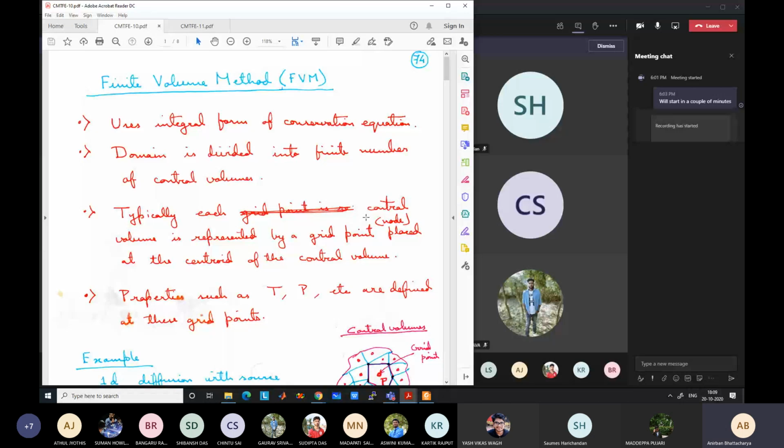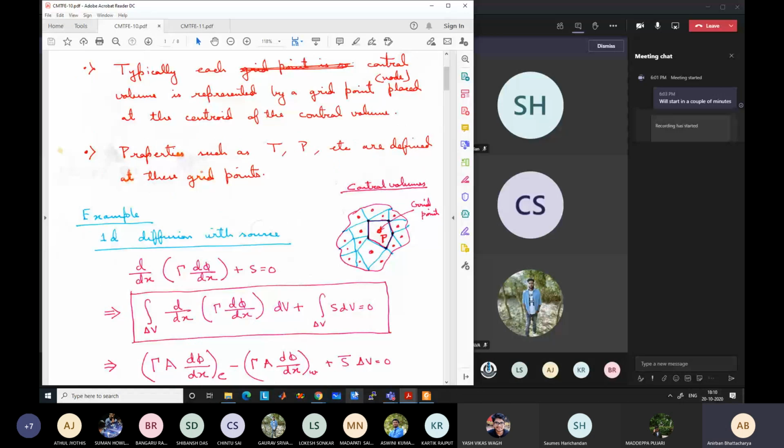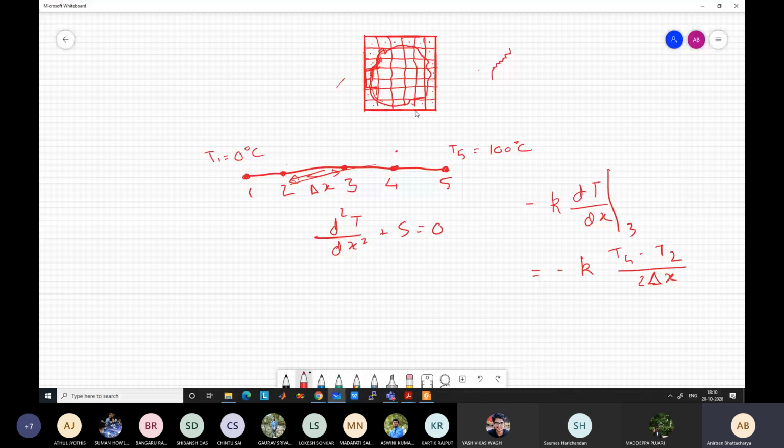But when you go to complex geometries, as we had discussed previously, there is a major drawback of the finite difference method, because it cannot tackle complicated, irregular boundaries easily. It can be tackled by some sort of interpolation. You have to take a larger domain around the actual domain and then modify the governing equations so that you put something outside the domain also, say some properties with conductivity 0 or viscosity infinite, so that no flow can occur there.